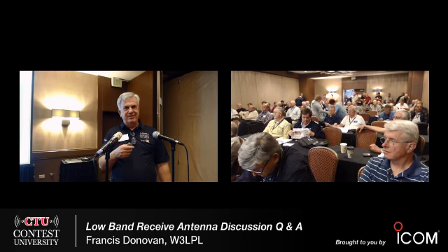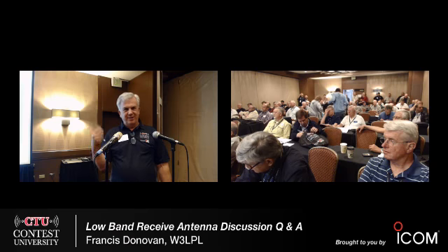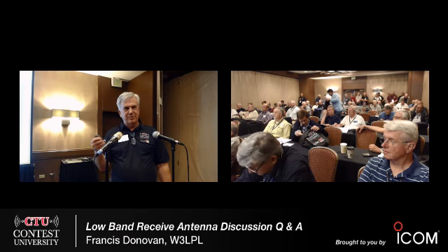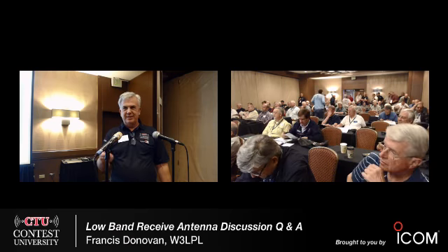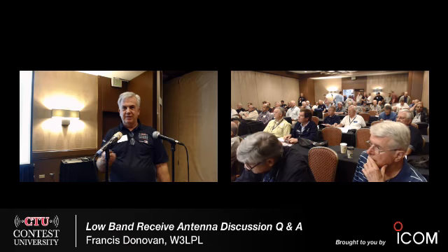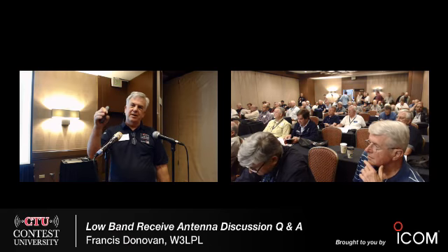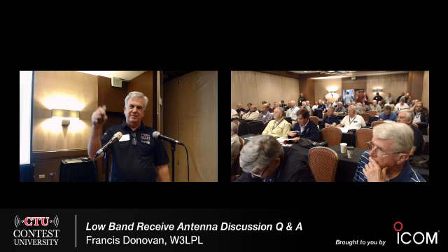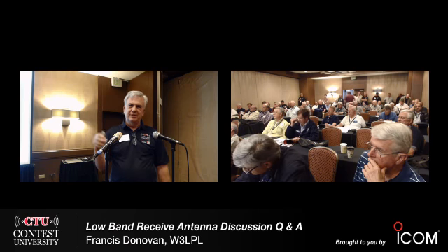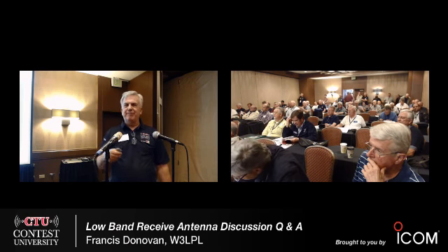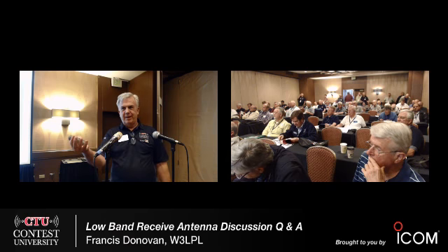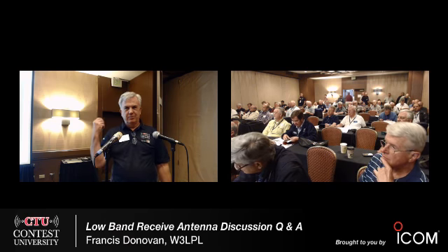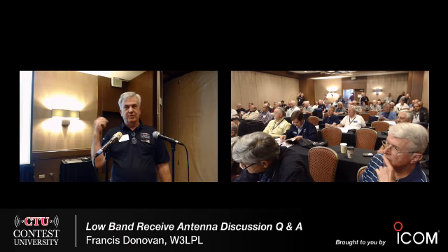I don't really like that answer, because I'm going through all the trouble to get a really good receiving antenna, and now somebody's telling me I can build a compromised antenna that will cover 2 bands pretty good. So yes, the high Z antennas will cover 2 bands, pretty good performance. My preference is to build that antenna and build it optimized for 1 band. So, and the low impedance verticals are definitely for 1 band only.